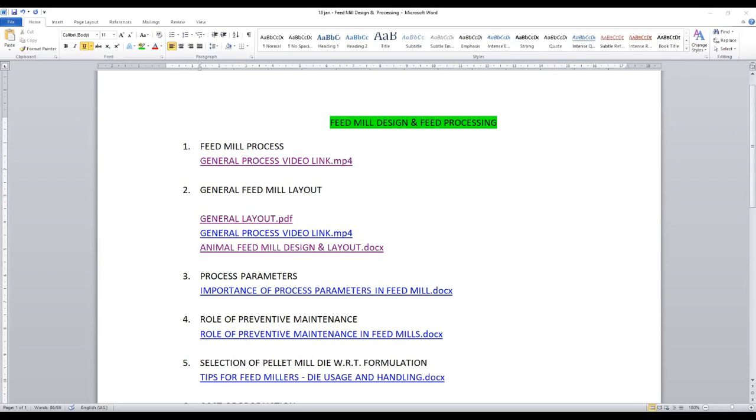So that is the weighbridge. Boiler chimney height norms are as per the boiler and the government norms. For example, in Haryana the norms say the chimney should be up to 27 or 30 meters. Before installing a feed mill, you have to check with your local norms and the government regulations, what the government requirement will be with respect to the chimney norms and the dust emissions. For example, in the nearby NCR region in India, the government...